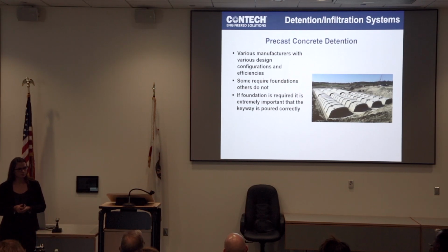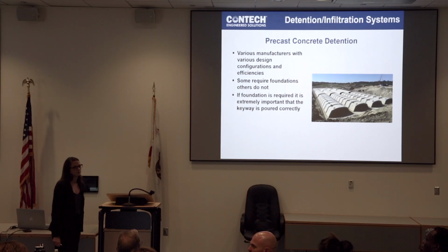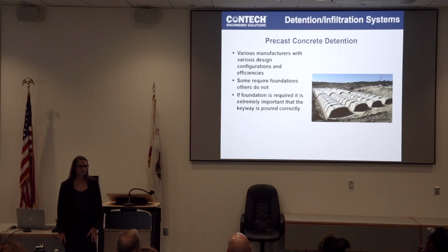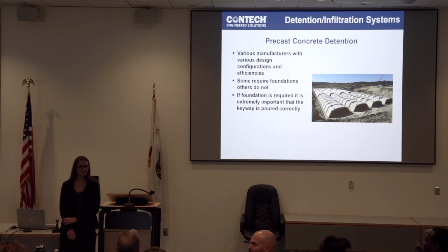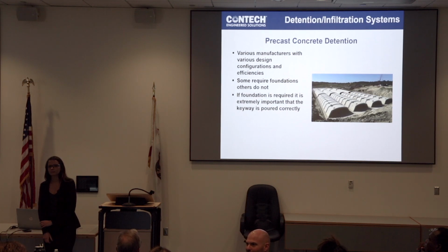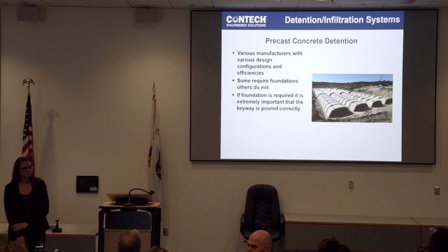So the thing with concrete, and I'll just say it, is most of the time designed correctly, precast concrete is going to be something that you can pretty much drive over almost instantaneously. Vehicular loading, you still want to watch for backfill that it's done properly. Some people will design with concrete thinking, okay, it's concrete, this is kind of the top system that we can put in. But the mistake that is commonly made is they don't properly backfill. So though that structure doesn't move and it's sound, the backfill isn't. So you'll actually have a failure of the backfill areas, not the structural area of the superstructure itself.